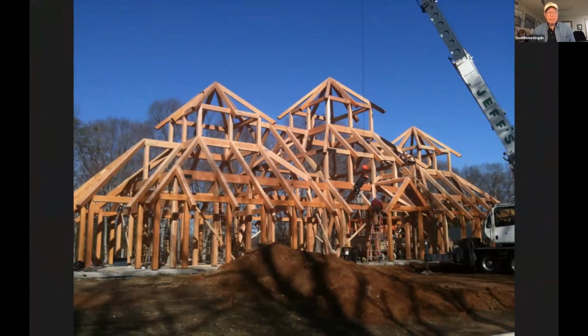Okay, well, this slide is a good illustration. It may or may not apply here, but normally these timber frames are decked, I would say more commonly, with 2x6 tongue and groove sheathing. And as you all know, it has a limiting diaphragm capacity of about 70 pounds per foot in allowable stress design.